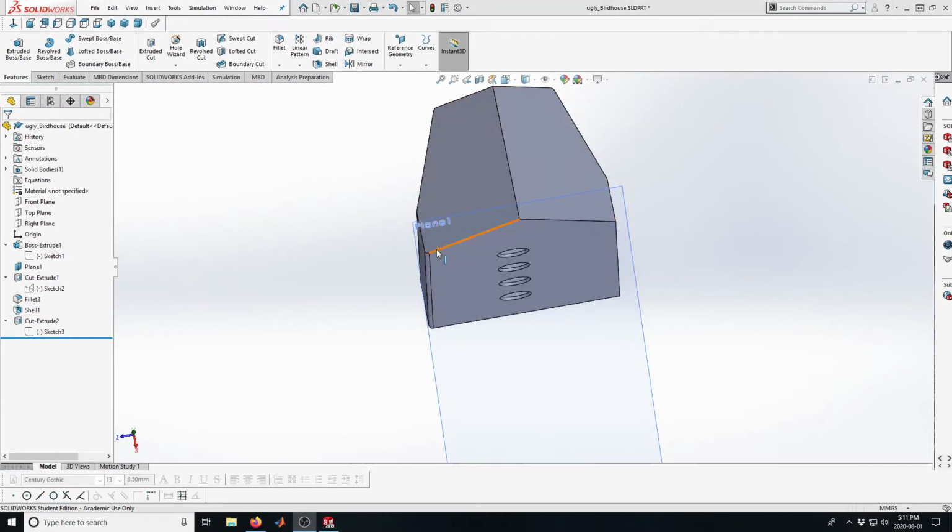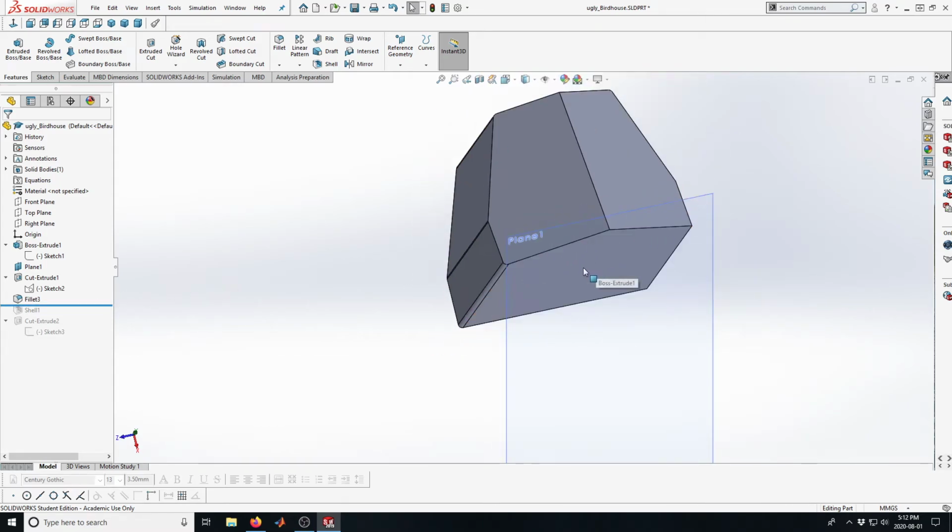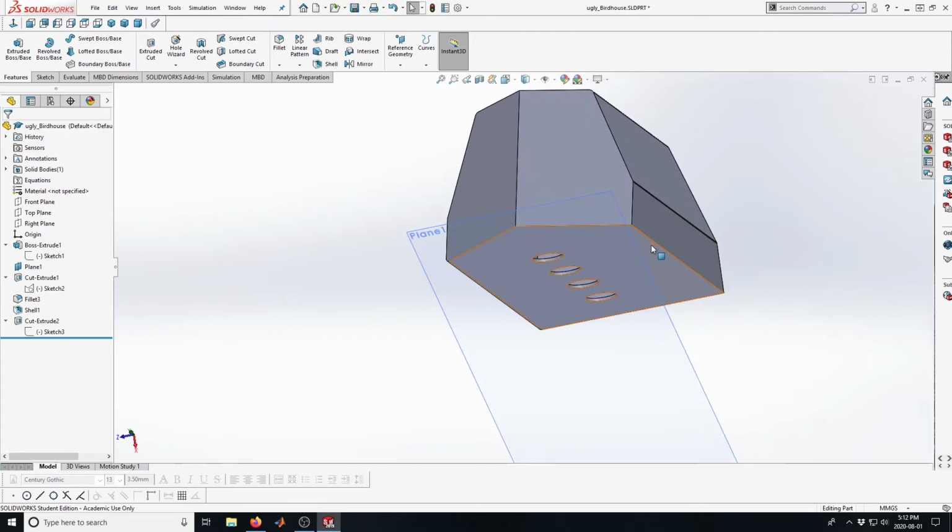Now, I've added these fillets, and I just did that by rolling back up here and inserting a fillet. And I put those in because my plan is to make something that I can fold around these corners. So just to remind myself that I'm going to fold it around those corners, I put those nice fillets in. And I left this corner sharp, because that corner will be where the thing comes together. I could have picked a different corner, but that's what I did.